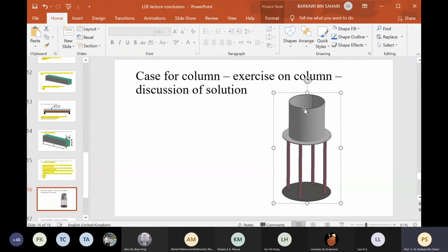So in order to calculate the length, one quarter of the weight of the column of the liquid is the critical load of the column that we want to use to support it. If you use a longer length, it will definitely buckle. So you have to calculate the maximum length that you can use in order to support this tank with the liquid in it full, and you have to decide on the length so that it doesn't buckle. So that's what the question is all about.